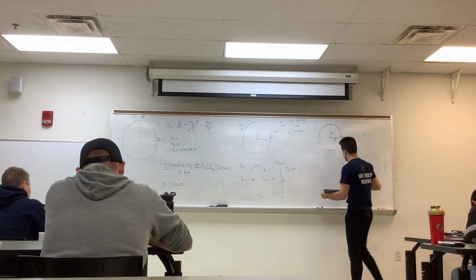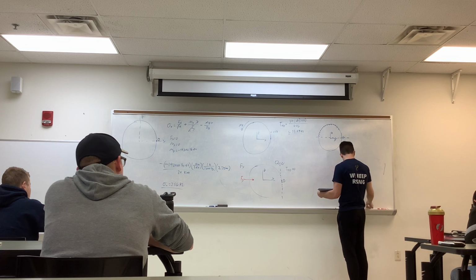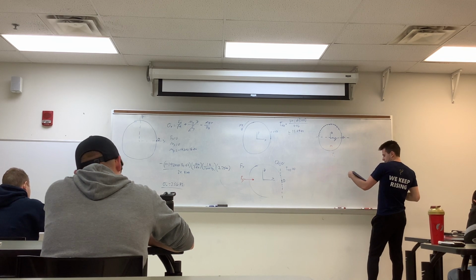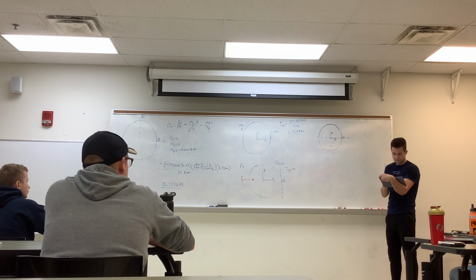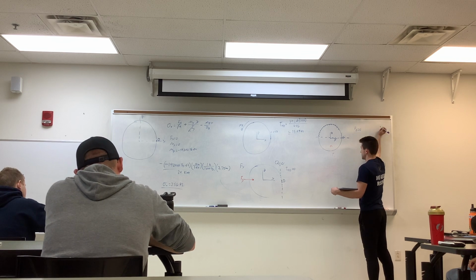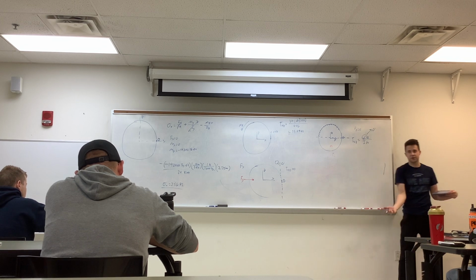And this is all with regard to our force in the z. But in this case, when we did our free body diagram, we found that our force in the z was 0. So from our full free body diagram, F of z equaled 0, giving us, we didn't even have to do this equation, tau xz is equal to VQ over Ib, because this turned out to be 0, giving us no shear in that direction.